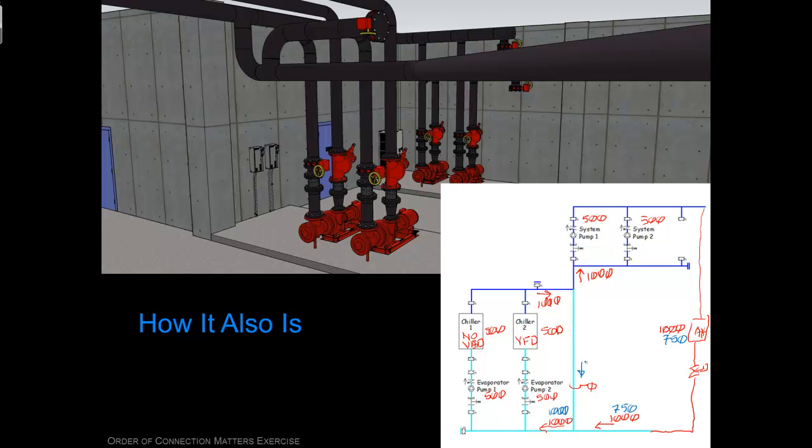So at part load, you start to reverse flow in this plant design, and that takes cold water from the discharge of the chillers and mixes it with the warm water coming back from the loads. And so that means this temperature goes down, and that's fine. This temperature goes down.